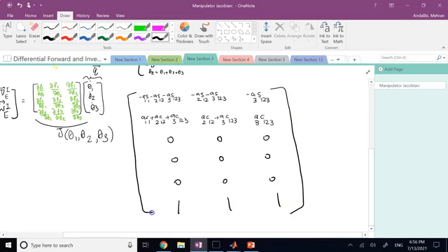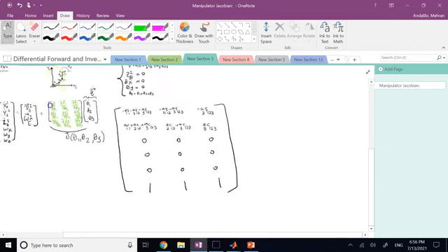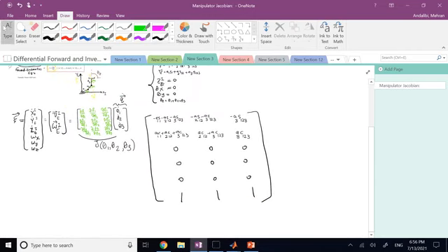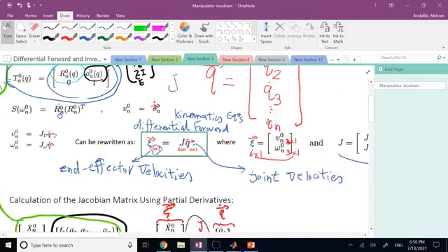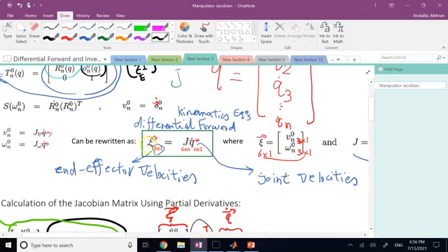Okay, so if you really treat the end effector velocity vector in 3D, then this matrix J in general is not square. The dimension of it in general is 6 by n, because zeta, the end effector velocities, always has 6 components, but your joints are not always 6. Sometimes your robot has less than 6 joints, sometimes exactly 6 joints, sometimes more. For example, the 2 or 3 DOF planar arm or SCARA, they have less than 6 joints.